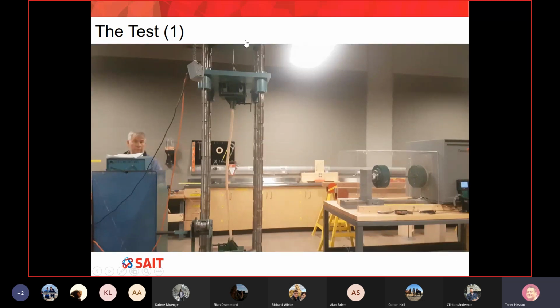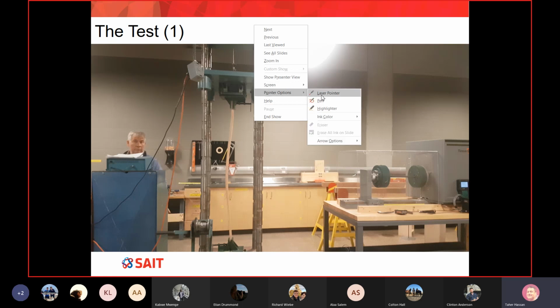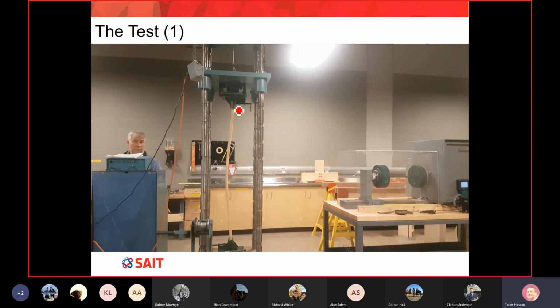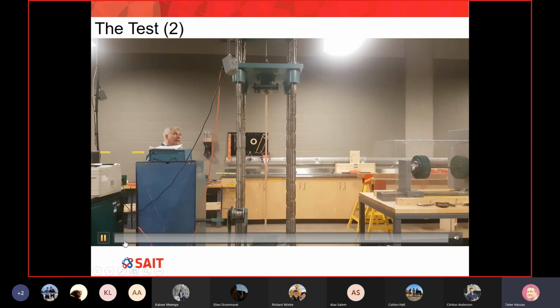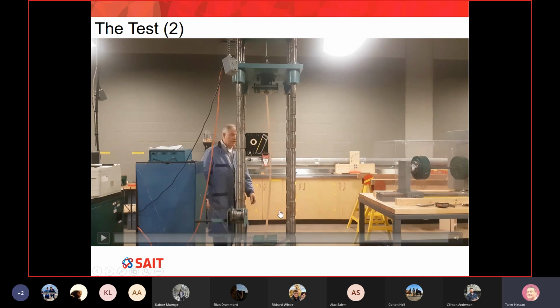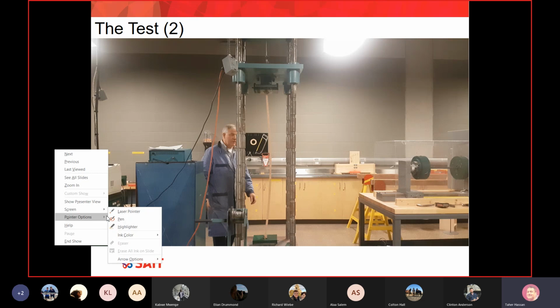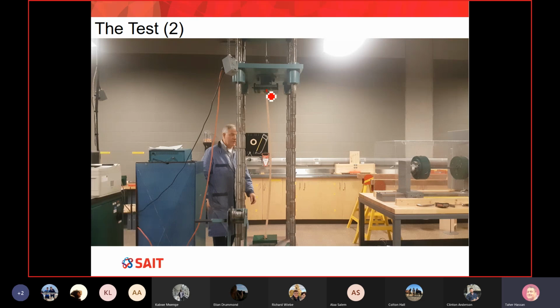You can see, because of this bracket, let me turn my pointer. I'm not sure if I can write something on the video. Okay, so this is the bracket. And see the column goes straight, and then here it decided to make a curve, kind of a sine wave, and then come back here. While in the other video, if we start the video and go to the end, what happens here is that the column starts buckling from here. You can see the curve starts from here and goes back to this point. So we have kind of full length buckling.